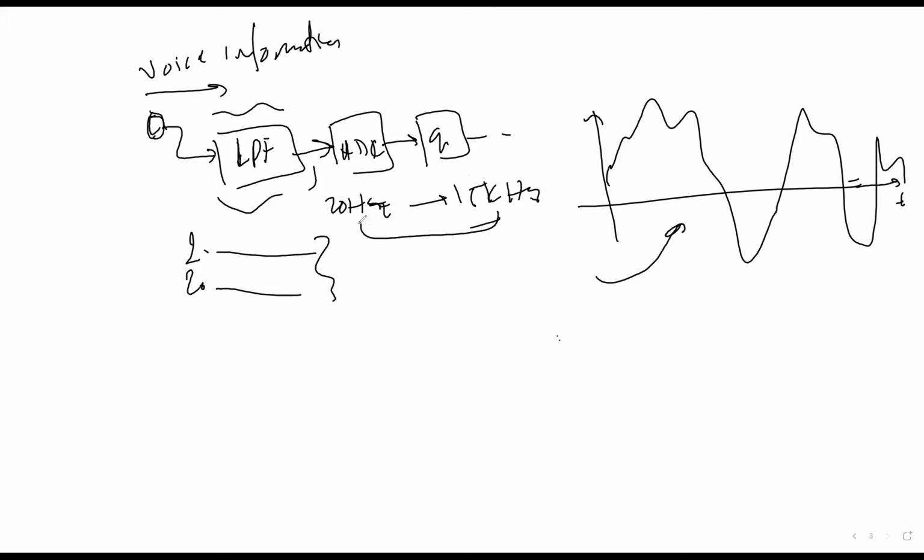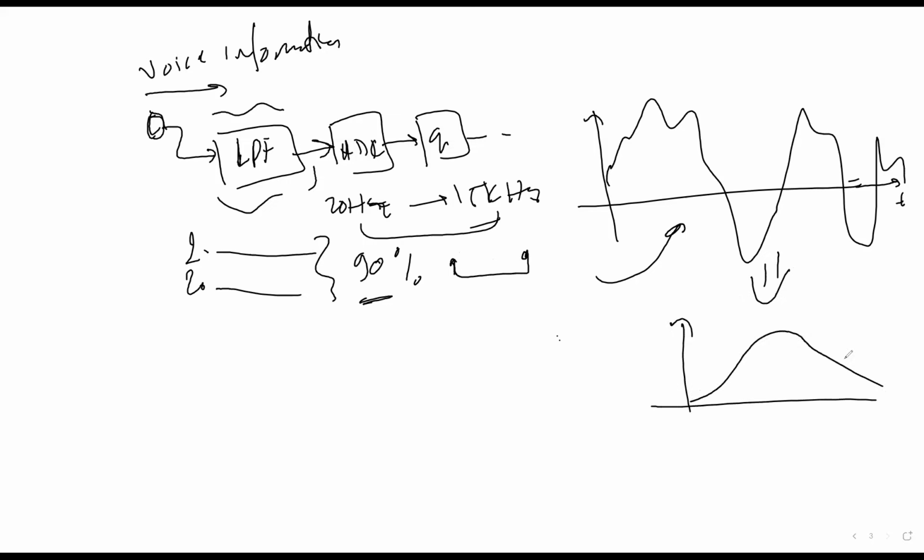So I need the spectrum where I can send 90% of the probabilities of the changes of the signal, or 90% of the energy of the signal, based on the frequency domain. In order to solve this problem, I need to convert this random signal into the frequency domain. Because this signal is a power signal, its energy is infinite, so we need to take some time sample of it, and then we need what is known as the power spectral density.